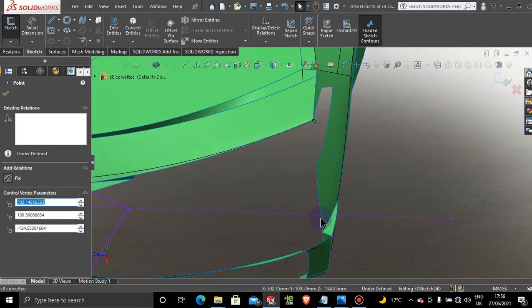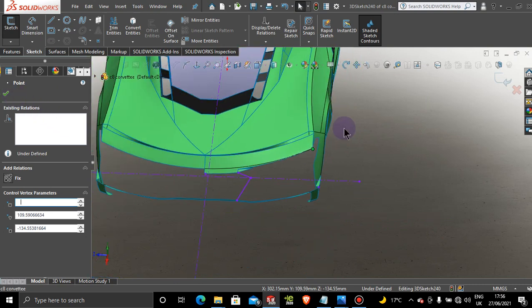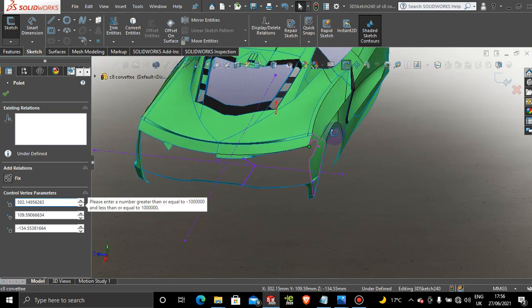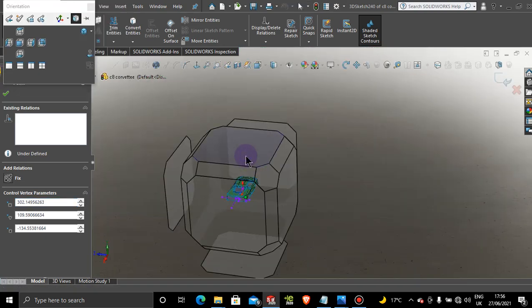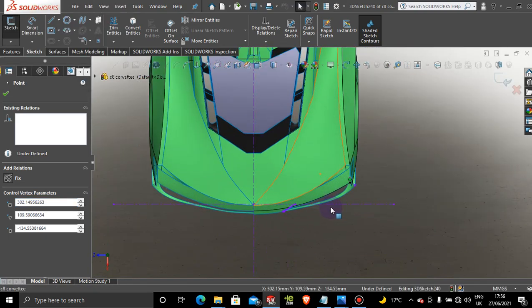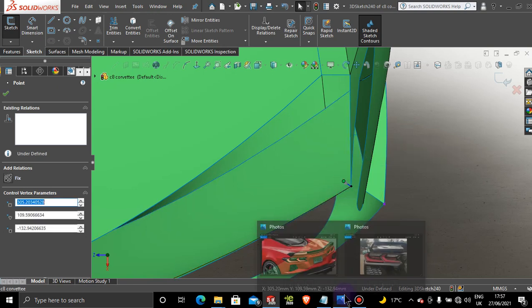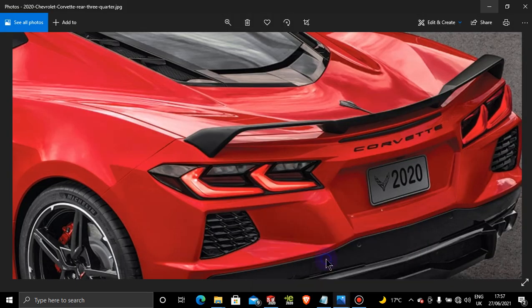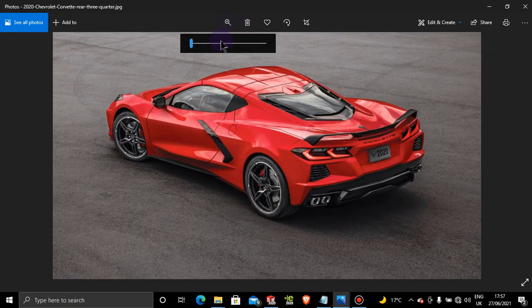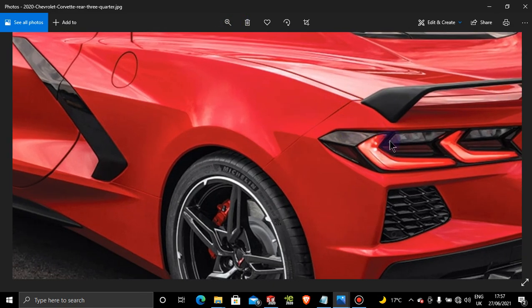So now it's under the car. I'm pressing the space bar every time you see this cube here. And then I'm going to grab this point and pull it onwards here. So about there. So let me show you why I'm pulling under the car. I'm pulling under the car because that curve that I just added is this curve here, and it goes underneath the car.